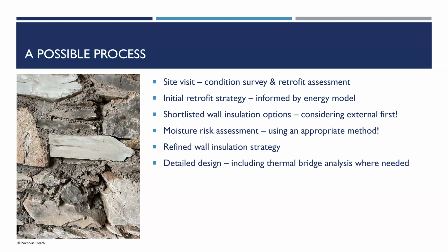You then carry out some detailed design. Make sure you sort out all the defects and get the building retrofit ready. That's a really good phrase to remember. Again, as with understanding, if your building is dry and sound and free from defects, anything you do to it is going to be lower technical risk.